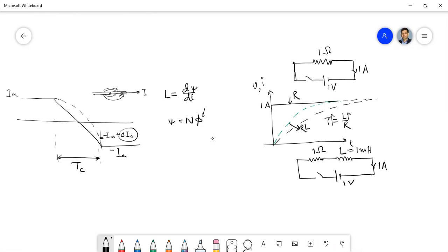Okay, so the armature core length is another factor. Not only that. Suppose we see some coil, so coils are like this. This portion is also important, not only this length. So the length of the actual coil depends on the armature core length, and also this overhang length. This overhang length depends on the pitch of the coil.